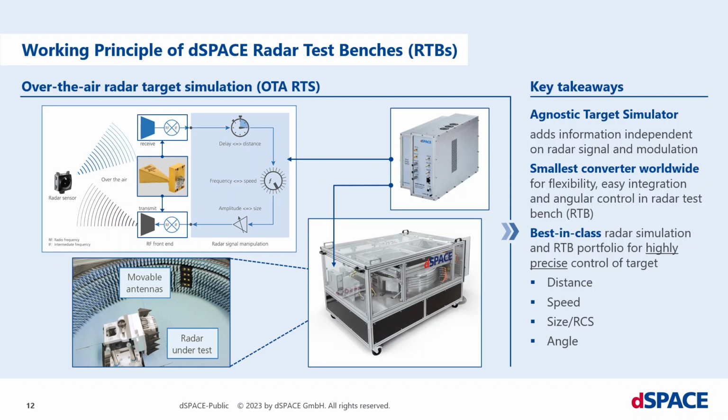We do not have the time to do any analytics because any processing delay will cause additional simulated distance with the speed of light. This is why we call DARTS an agnostic target simulator. We do not need to know anything about the radar signal and modulation.